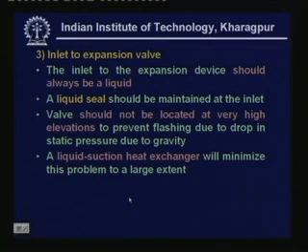So locate the valve at not very high elevations, and a liquid suction heat exchanger will also minimize this problem to a large extent. So these are the practical problems and practical points to be considered while using and installing the expansion devices. Thank you.